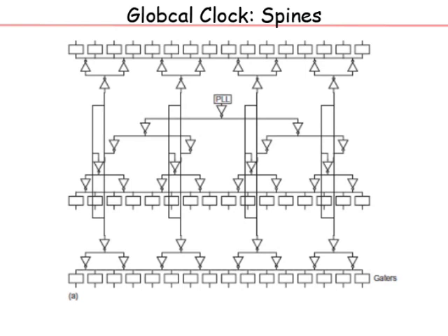Pardon? Pulse width will not be affected. The rise time will degrade a little bit, because let us say you have one edge coming here and one edge coming here a little later. Let us say the rise time of the first edge is maybe 10 picoseconds, the second is 10 picoseconds, but there is a little spacing between the two of maybe 5 picoseconds. Then the effective edge rate at this point will be in between the two edges.